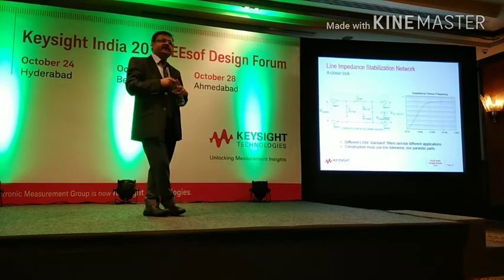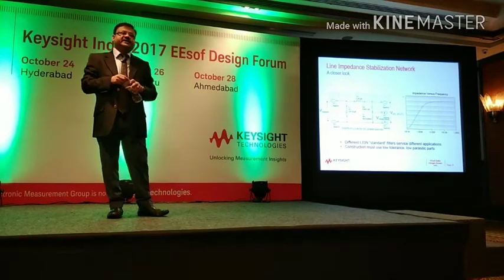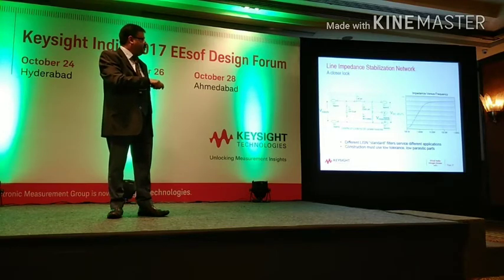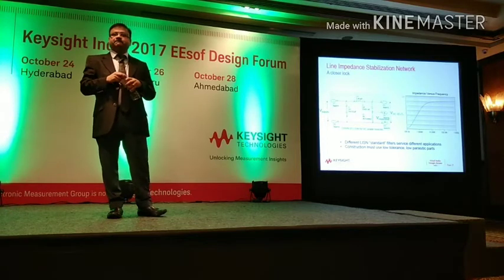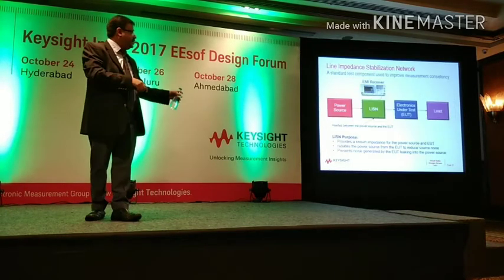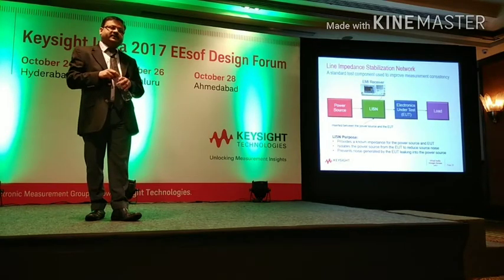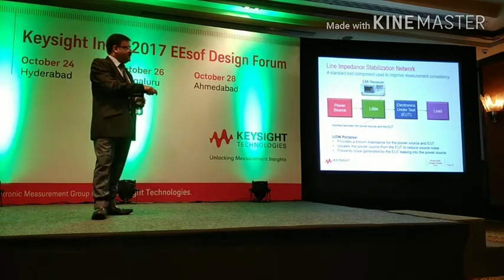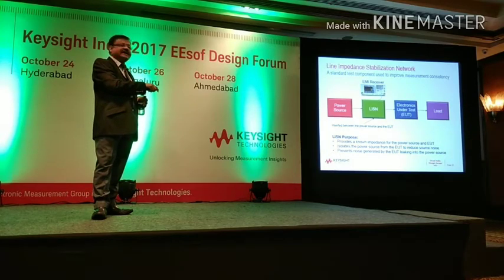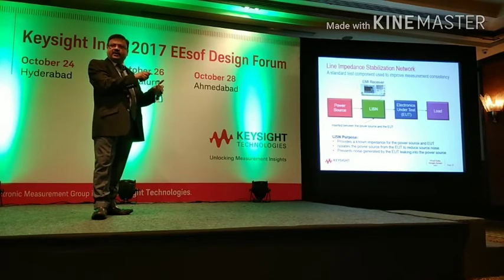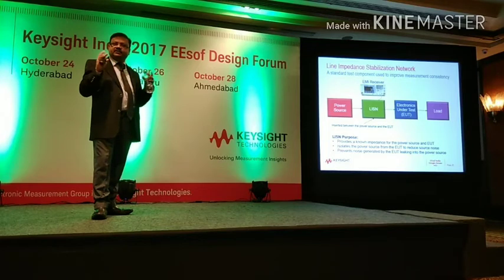If you have to create an equivalent of that in a simulation environment, here's a very simple topology of a LISN. You have a supply, you have a VDC output, and you can plot impedance versus frequency. So if I have to replicate this process in the simulation world, this is my design. This is an ideal DC source, ideal or non-ideal DC source. So these both I can control.